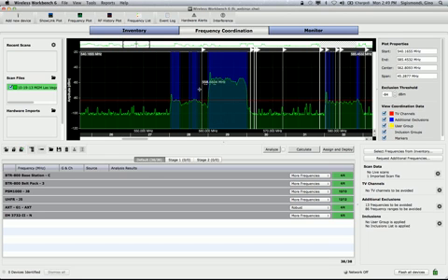This frequency here looks like it is compatible, but it's very close to some energy right here, this scan peak. You can actually move markers around in Wireless Workbench 6.11 and then reanalyze things to see if they're compatible. That one's obviously not compatible now because it's red, but I could move them around in a variety of different locations so that you can coordinate frequencies visually as well, using that human element of expertise.